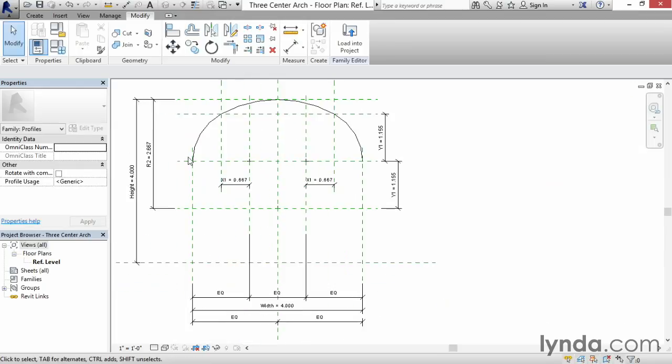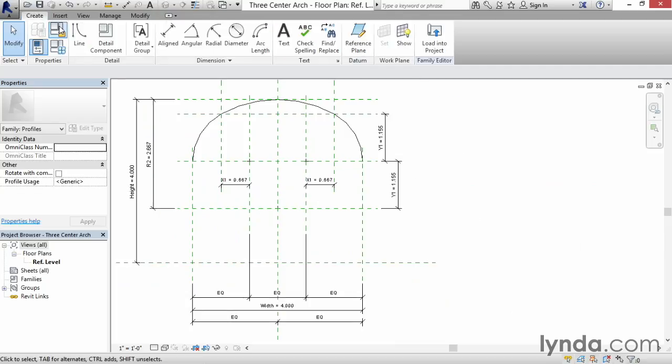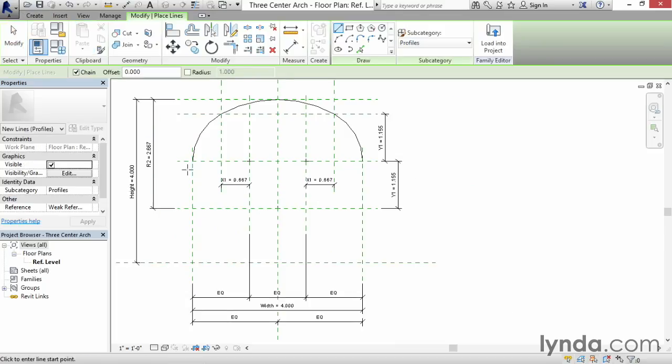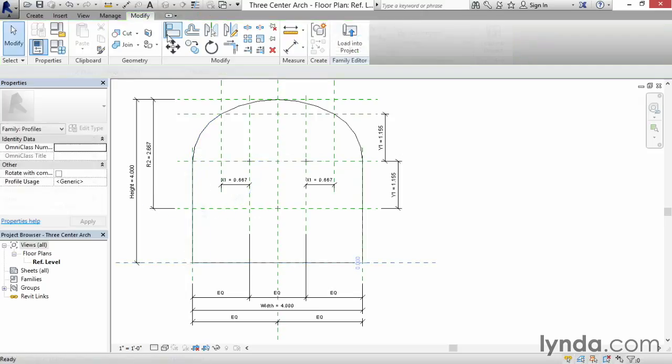So now I just simply need to add 3 straight lines down around here. And don't forget to align and lock it. Remember, it's reference plane to line. So when you're done, it should look something like this. Go ahead and flex it one more time just to make sure it's working, and then save it on your desktop, and you'll have it ready for the next movie.